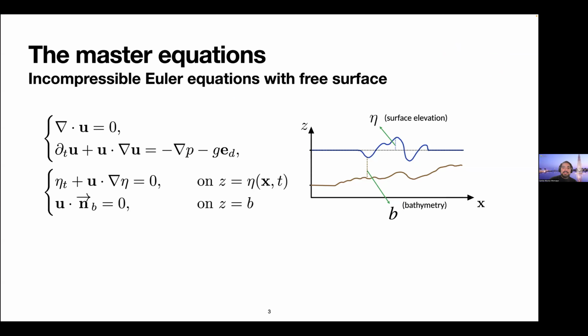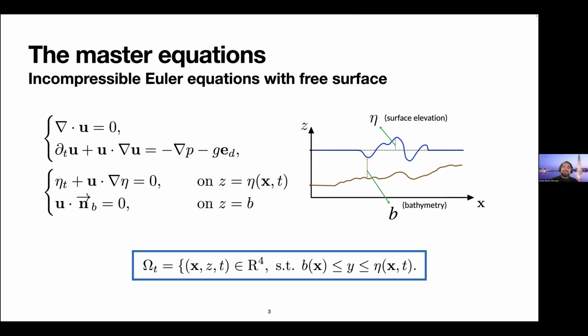Allow me to start with a bit of an introduction on this type of equations. So we know that under reasonable assumptions, the surface water gravity waves are described by the Euler equations. Ideally, we will use this set of equations to model tsunamis, but the boundary is moving with the flow. So to develop large scale solvers for this set of equations that are also robust and efficient is just not feasible at the moment. That is why we use simpler models.